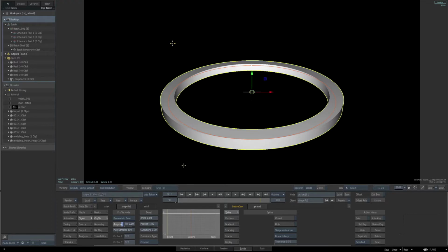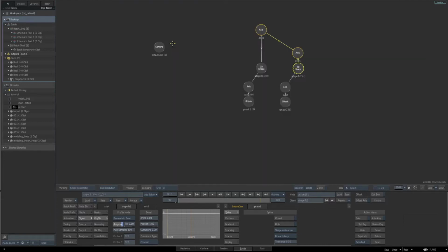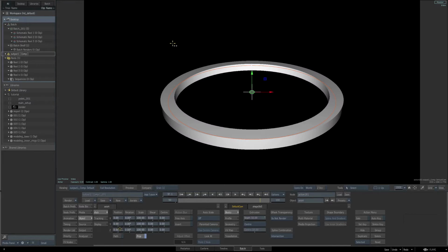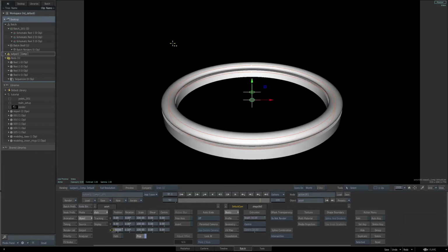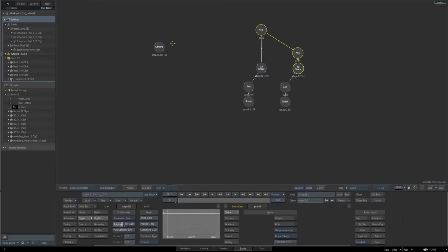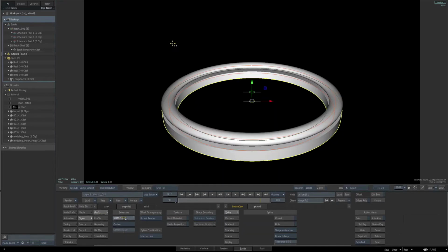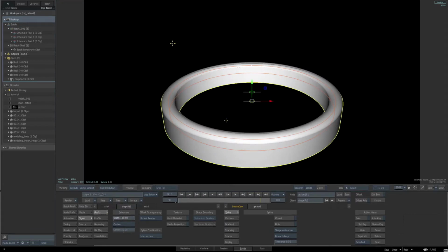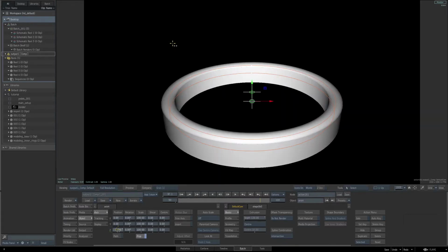And then holding the Control key, click in the angle and the curvature parameters for the bevel to reset them. Go back to the schematic again, select the top axis for this shape. I'll drag it down to -58. Go back to the schematic, select our 3D shape again, and then let's go to the basic settings for this object and change the depth for our extrusion for this shape to be 120. Once again, select its axis. We want to line it up with the other geometry, so I'll set the Z position to -63.